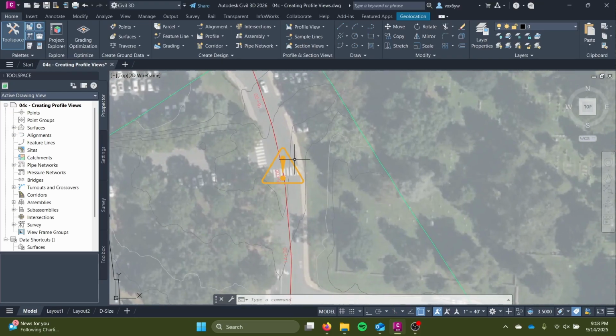The one here you can see is on the alignment, and it's because the tangency is violated. If you recall how this alignment is made, you draw tangent lines that intersect at PIs or point of intersections, and it draws a curve of constant radius between those tangent lines. But when I made this, I had deleted some of it and then added onto it. And when I added onto it, the tangency that the alignment was using wasn't saved, isn't the right word, but it wasn't maintained as I went along.